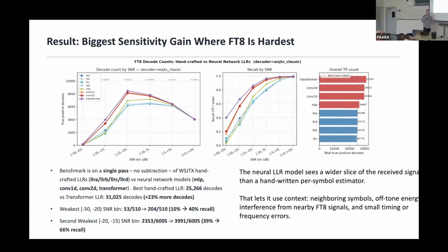There's an experiment I did that I didn't show, where you put all of these symbols on something called a trellis, and you can propagate phase knowledge across all of the symbols. Why limit yourself to just 3, since then you have to do 3 all in a block? The problem with that analytical method is that the complexity blows up with n. You have to do 512 different combinations with n equals 3, and then 4096 if you're at 4, and it just isn't worth it anymore. But anyway, they're really, really close, I would say, if you're assuming everything is perfect.